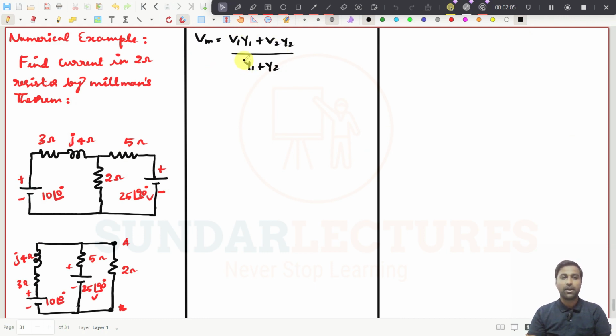So this is Vm. And what is Zm? Zm should be equal to 1 by (y1 plus y2). That's all. And you can replace these two branches with a single Zm and Vm, right? That is the whole idea. So you see, V1 is this one, V2 is this one, and you need to find what is y1 and y2. That is your ultimate aim, right?